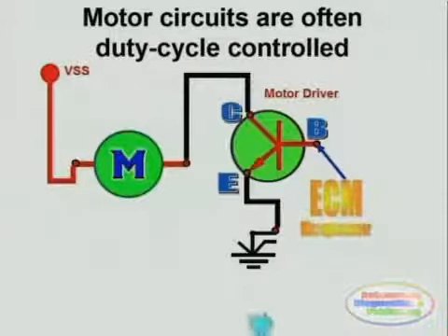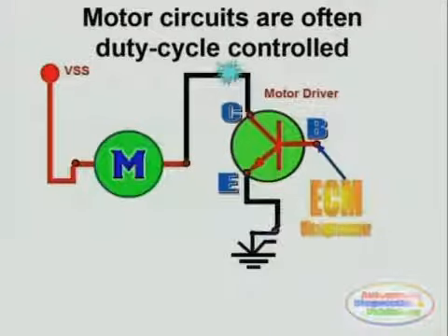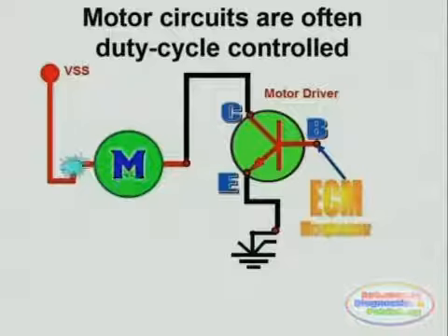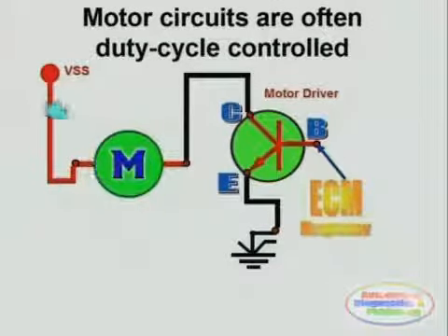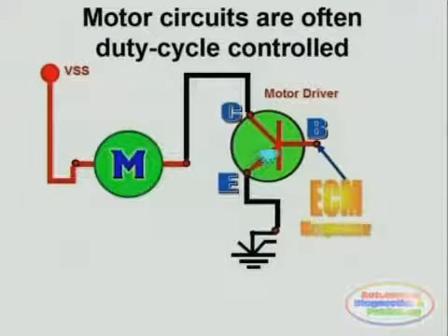The ECM microprocessor applies a very small pulse to the transistor base lead. This will cause the transistor to become conductive. In other words, it will cause the transistor to close its circuitry and conduct electricity, or electron flow, between the emitter and collector leads.